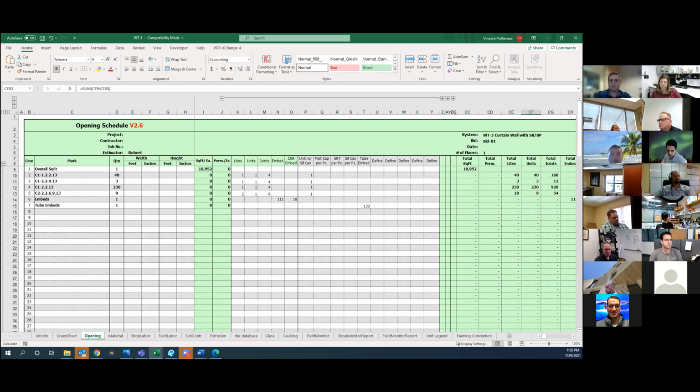It was interesting because when we talked to Pole and Americlad, they were in the same boat. They said, look, we really need 3 things. We need to know the total stretch out of the panel, meaning in its flat shape, what's the widest it is and the tallest it is. We need to know how many times you want us to bend it. It didn't even matter that we'd broken it up into horizontal bends versus vertical bends; Pole said we just need total bends. And finally, we need to know how many inches of weld you need us to do.